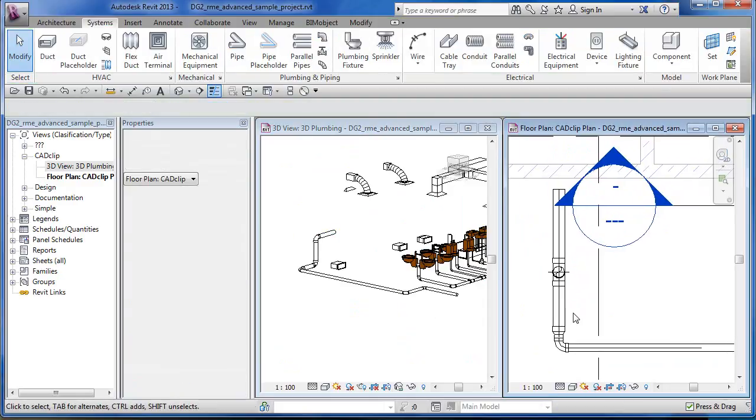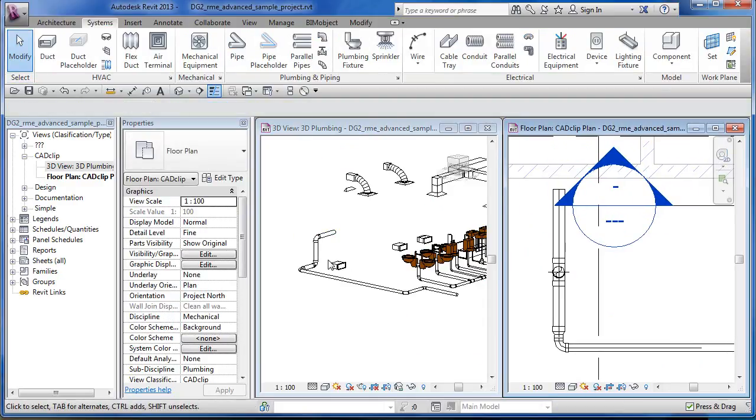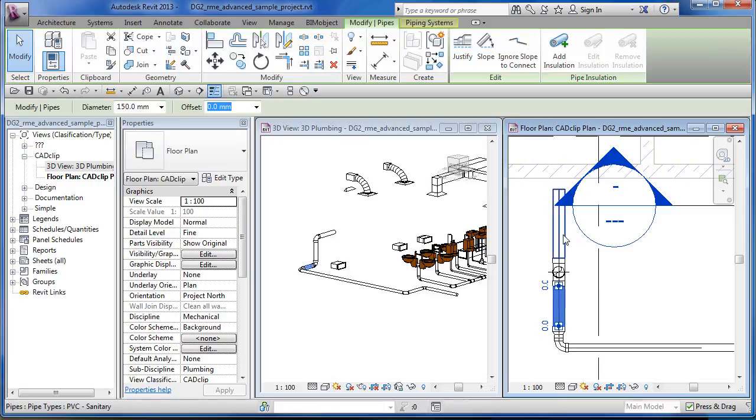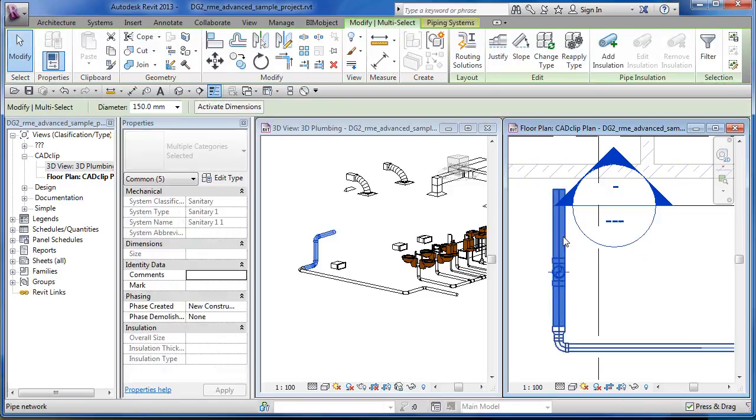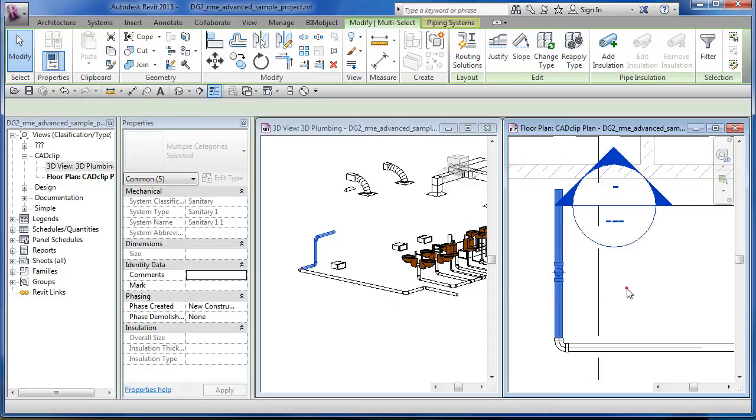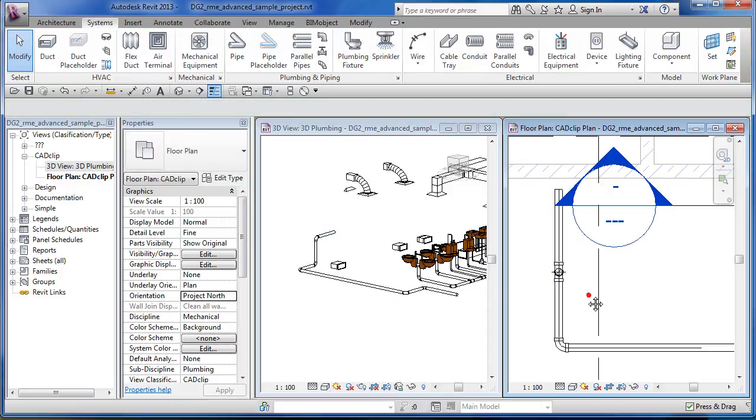Okay, so what do I do if I want to change that after the fact? Okay, watch what I'm going to do. I can do it from either place, but I'll pick on this segment. And then I'm going to hover up here and hit tab and then pick. And that'll pinch between those two segments. So if you hover over a segment and pick, and then go to another place, hover and tab, it'll pick the chain between there. Now from there, I should be able to go in here and say, sorry about that, you guys are 100s, and it's going to readjust it all quite nice.